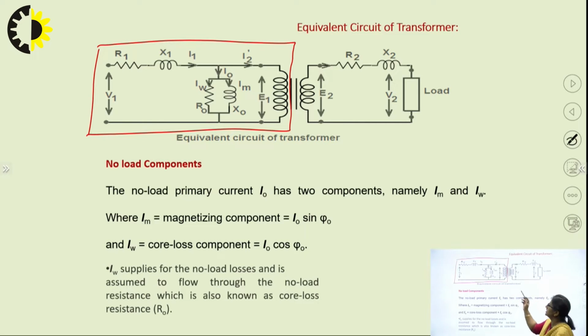So, this is the complete primary circuit of the transformer. Now, coming to the secondary circuit. Towards the secondary side of the transformer, the induced EMF would be E2. We know the relationship between E2 and E1. We have just seen they are related with the transformation ratio. Now, this secondary induced EMF E2 is driving our load, which is connected. I may be representing it with, say, ZL.